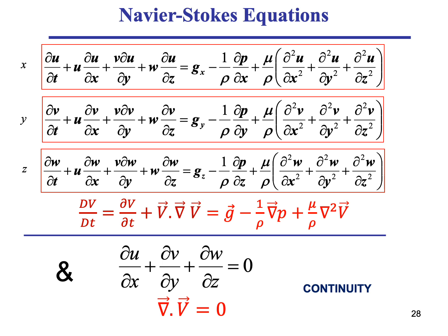So on the left hand side we have one term that has time in it and 3 terms that have a velocity times velocity divided by a distance. Both of them are called acceleration. The first one is called, we'll come to this later, local acceleration or time derivative, and the second term is called the convective acceleration, or the derivative moving with the fluid element, just because it's moving with the flow. But for now, these are accelerations.